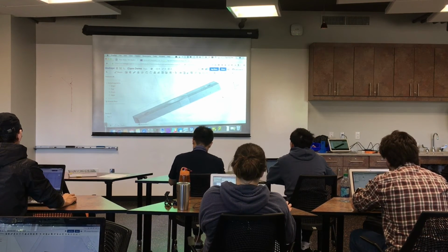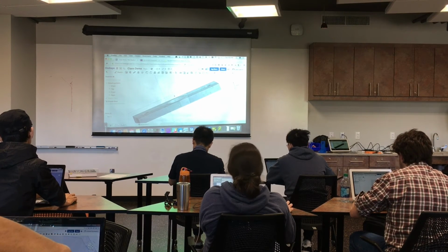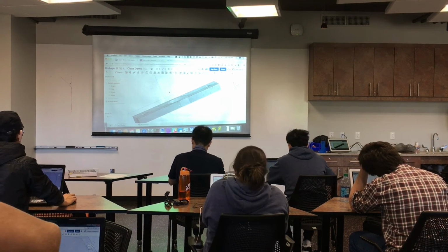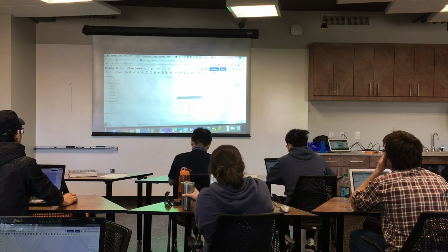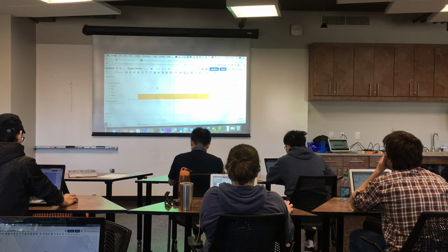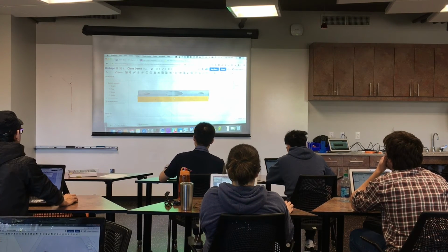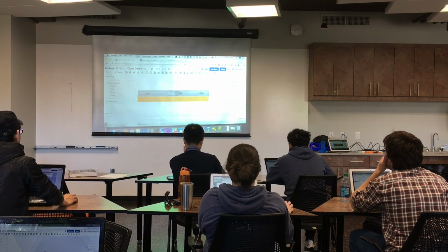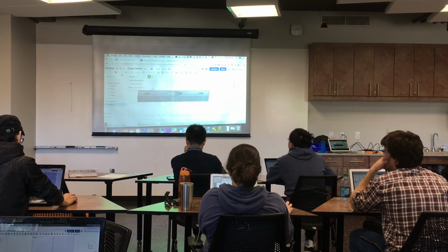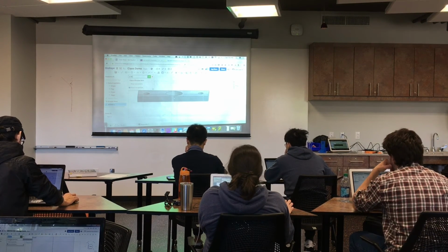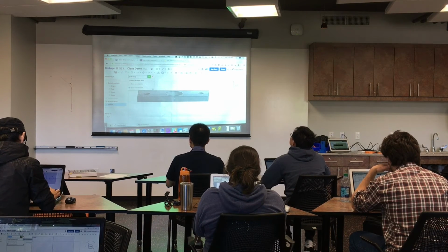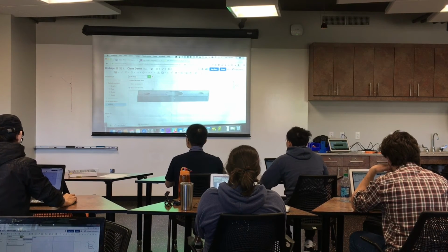There. Now we need to have this hole that goes into the part, into that center bit. So we're going to make another sketch, but this time we're going to make the sketch onto a face of the part. So if you click and select this front face so that it's orange, and click sketch, and we'll rename this, I'm going to call it 256 hole, because that's what it's going to be for a 256 screw.